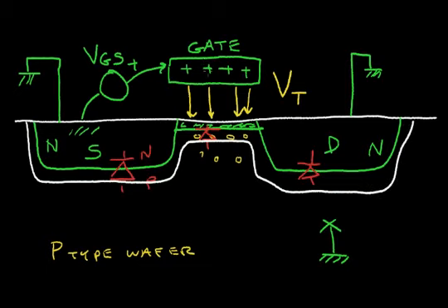So as we increase the gate voltage, we make this electric field stronger. And what we do is we shove this N region down further. And of course our depletion region extends down further. So as we apply more gate voltage, this channel region becomes thicker. It becomes lower resistance because we have a greater path for current to flow laterally in this region. Now, as we apply a very strong gate voltage, we drive this channel region down even further, and the resistance of this channel region becomes less, and this depletion region will be driven down further.